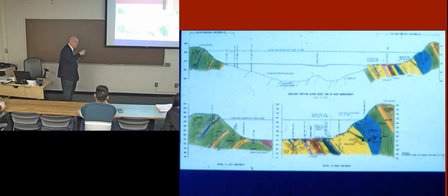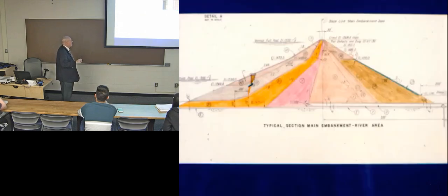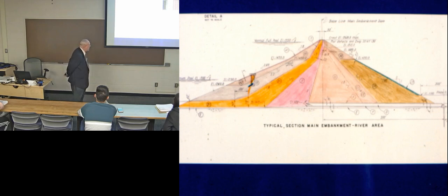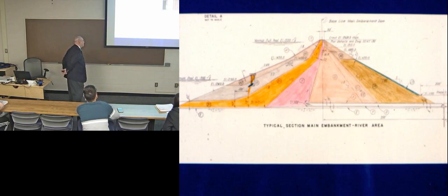So, in the design of this dam, one had to accommodate the fact that almost as much water is going to go under the dam as you spill out on the spillways. Important fact for the design. Okay, now here is a cross section. I'm sorry again for the fuzziness of the screen, but you don't need to be able to read it in much detail.